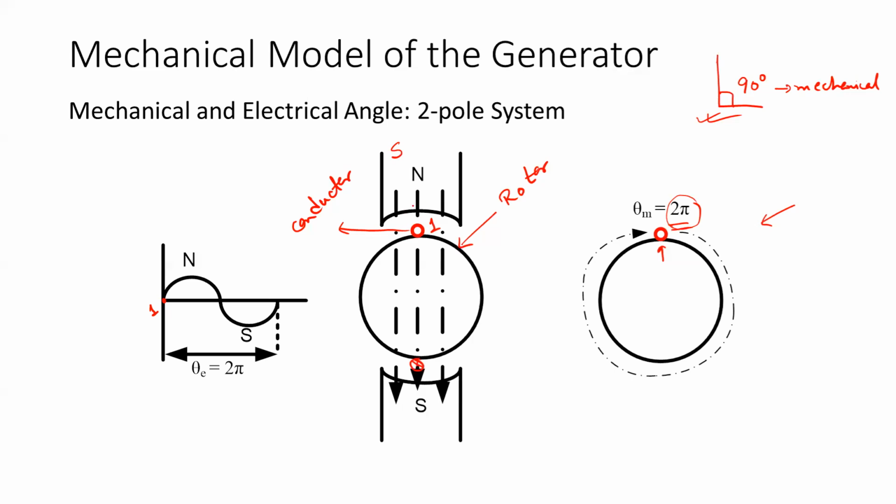Now, as we said, the rotor will keep on rotating. So as the rotor comes to position number 2, if your conductor is like this, where the plane of the conductor is horizontal and the magnetic field is vertical, that is where you get your maximum flux linkage. So if in position 2 you get your maximum flux linkage, that means in this current diagram you will get your maximum current, isn't it? Yes, sir. That means this is your position number 2.